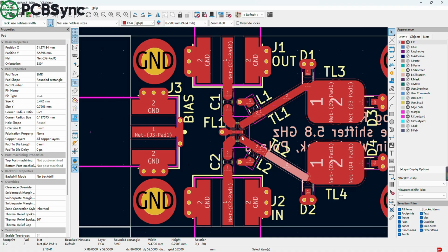If we want to switch it to RO4003C, we can't just swap the material. Just changing the material and keeping the original layout for production won't work. First, we need to reconfirm the board thickness because RO4003C comes in several standard thicknesses. Second, we need to recalculate the transmission line width to ensure the new stack-up still meets the target impedance.